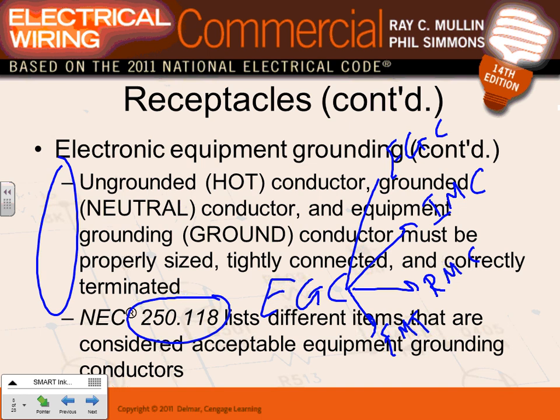Any comments, any questions about taking care of your electronic equipment by properly terminating the hot and the neutral, properly torquing them, properly grounding them, surge protective devices at the panel that feeds them, and properly providing an equipment grounding conductor based on 250.118? Any comments, any questions?